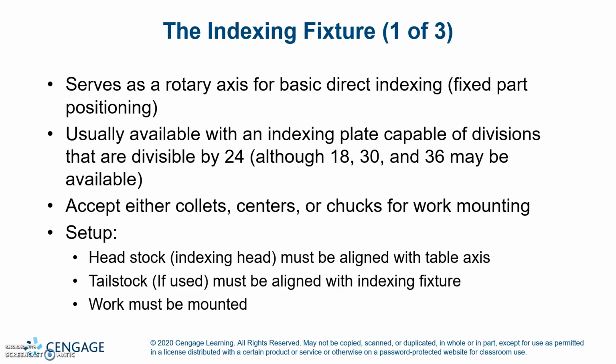The indexing fixture serves as a rotary axis for basic direct indexing, fixed part positioning. Usually available with an indexable plate capable of divisions that are divisible by 24, although 18, 30, and 36 may be available. Accepts either collets, centers, or chucks for work mounting.